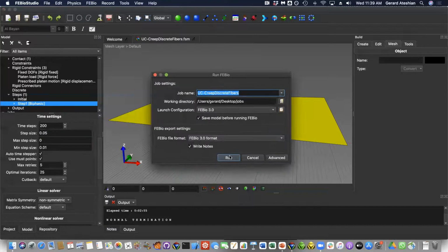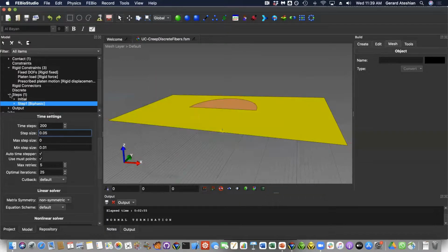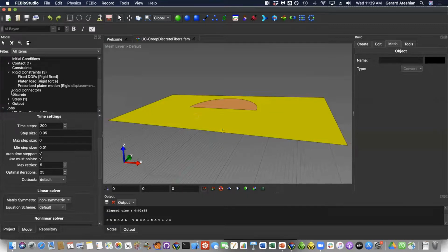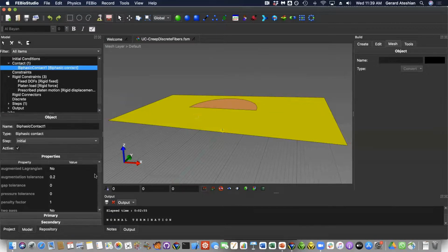Now, this will take longer to run. Oh, wait, I haven't added friction yet. Sorry. Let's go to the contact interface and do the 2 things I said in the slide. Let's change the friction coefficient. So the friction coefficient by default is 0. Let's make it 0.15. This is the equilibrium friction coefficient. And the solid on solid contact area fraction, I'll make it 0.1.